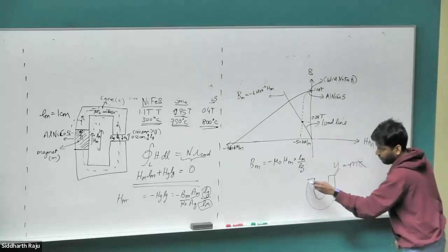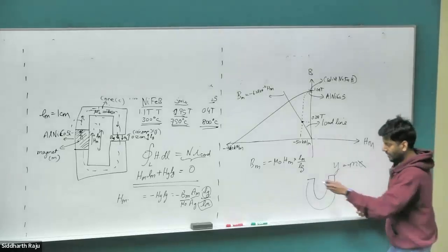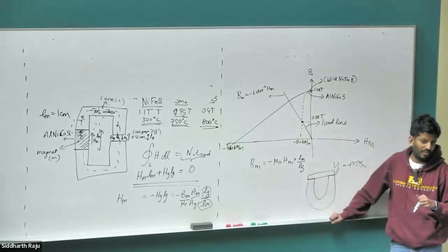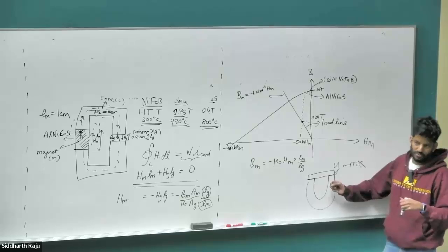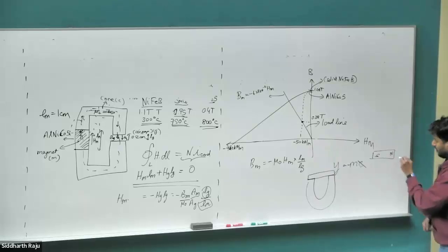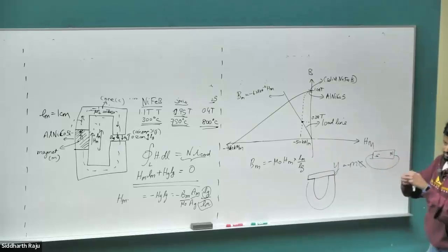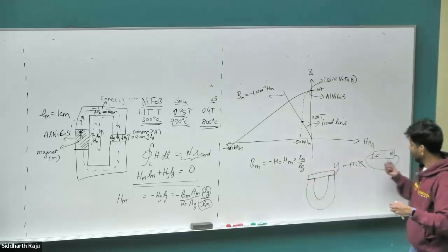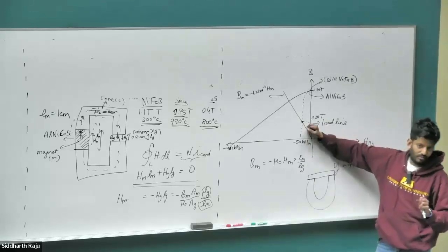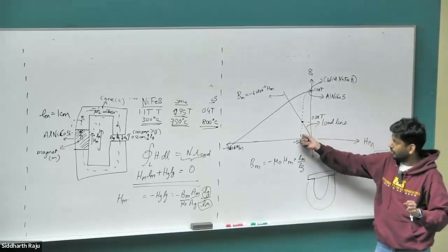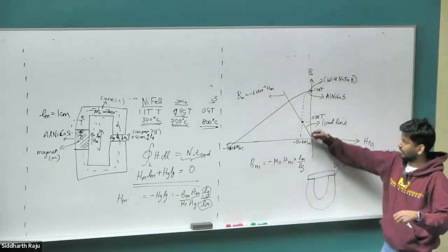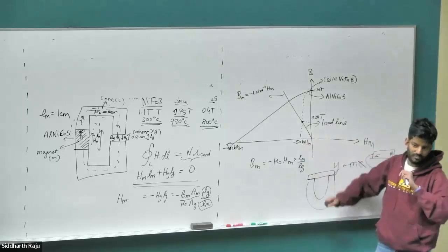This is the same problem that happens with other magnets. How many of you have seen a horseshoe magnet? Whenever you see these magnets, you'll see that there is a plate covering the top of the two poles of the magnet. There is a reason that this magnet is shaped like a horseshoe. With a typical bar magnet, if you have a magnet this large, the separation between the north pole and the south pole is very large. That means the air gap distance going from north to south is very large. If the air gap distance is very large, then the magnetic field will come down significantly. And if it comes down very low, then the external stray magnetic field of a nearby current carrying conductor or the Earth's magnetic field can completely demagnetize it, because if it reaches the coercivity point, the magnet is fully demagnetized.